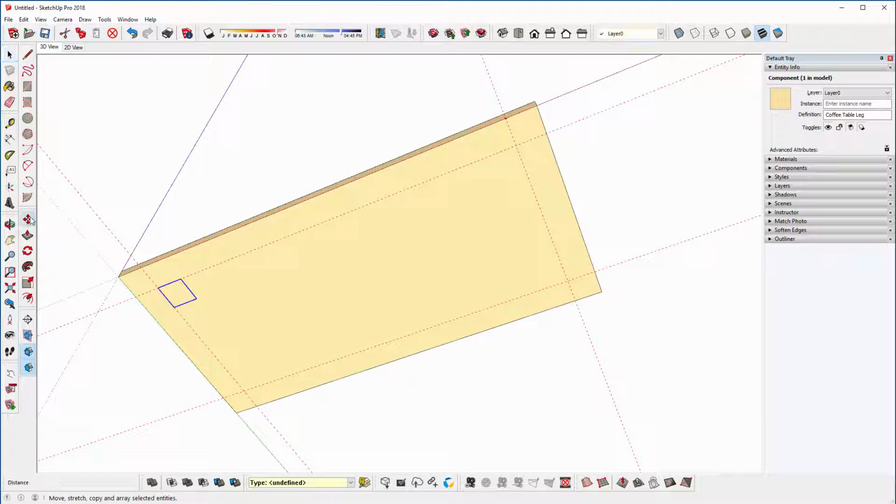So with the move tool, press Control once while the object's selected. Click on the endpoint there, drag it off to the side here, and click. Then again grab the select tool, then either Control or Shift, click on the other object. So we want to select both at once for copying. Again with the move tool, press Control to give it a plus next to the move tool, then click and drag that down until it intersects with the other guidelines.